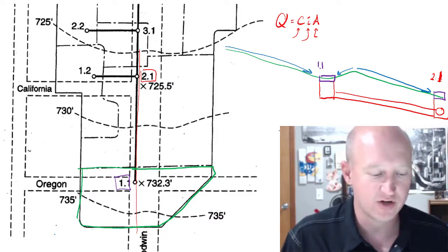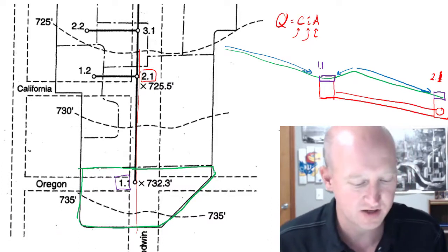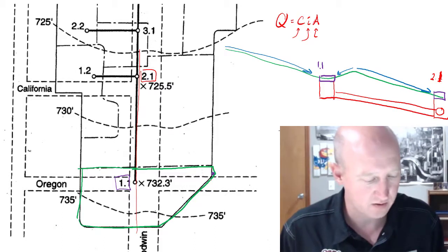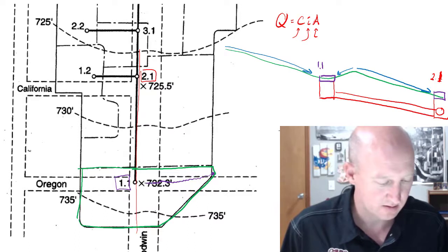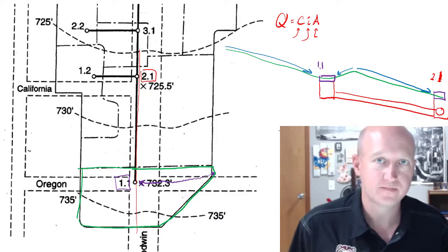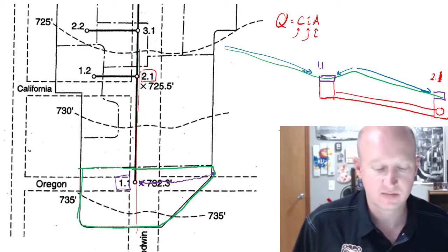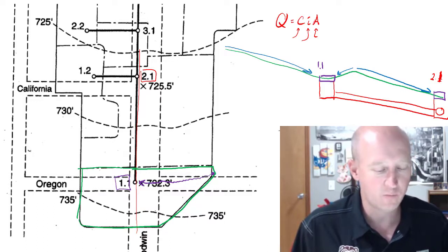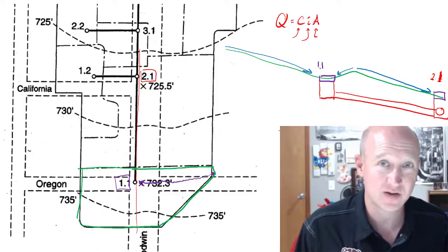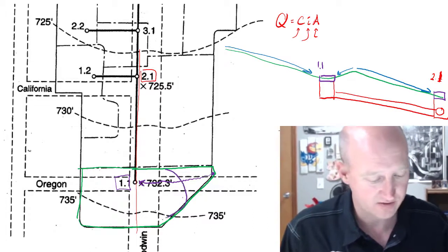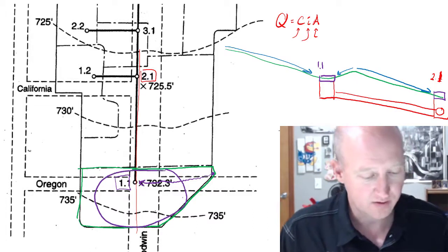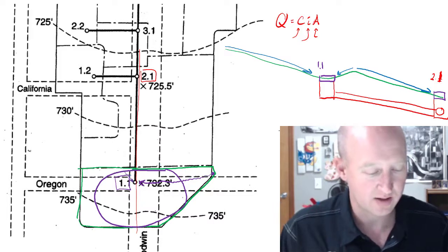So the time of concentration just describes how long it would take for water from the farthest part of the area to reach the inlet. And the reason is, if we chose a duration that was less than that, then we may only actually have this area within the circle draining to our inlet.